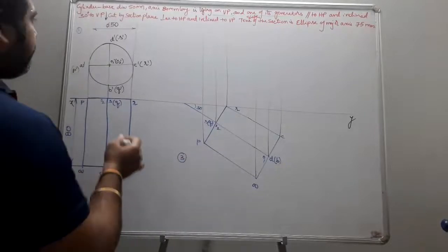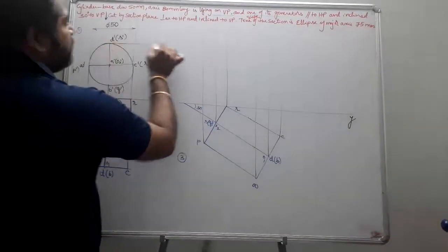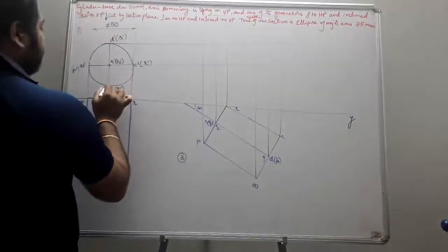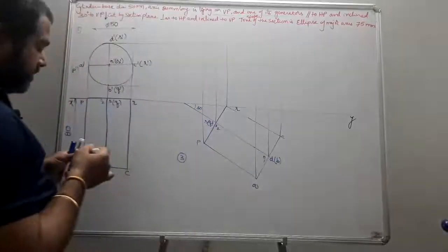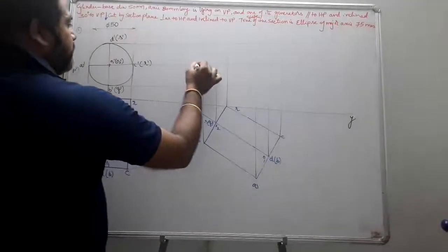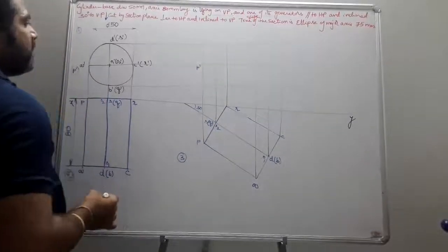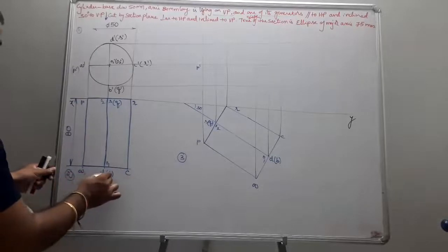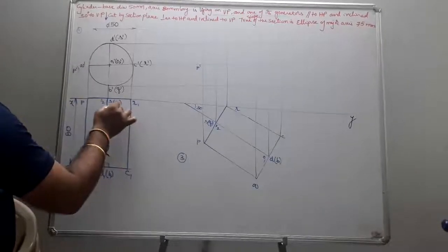Okay. And from here, draw the horizontal projectors. I'll mark the intersection points now. So this is P dash. So this was the second stage. I just considered this was stage 1. So let us give the suffix as 1. No problem.